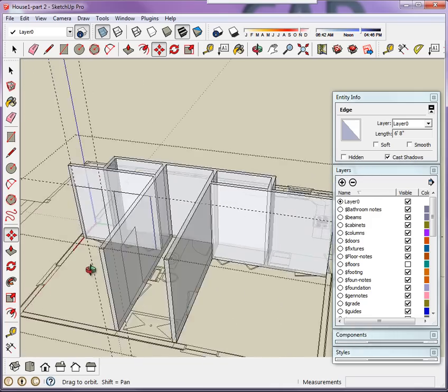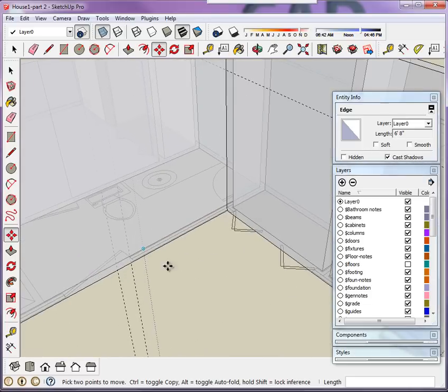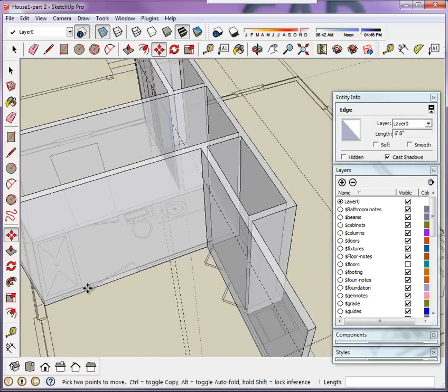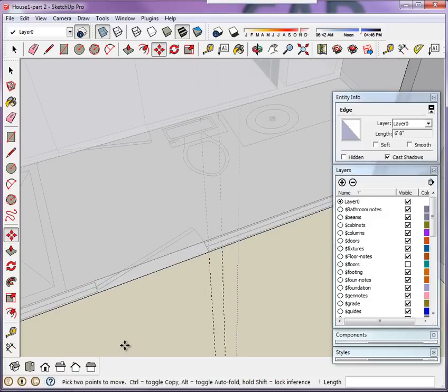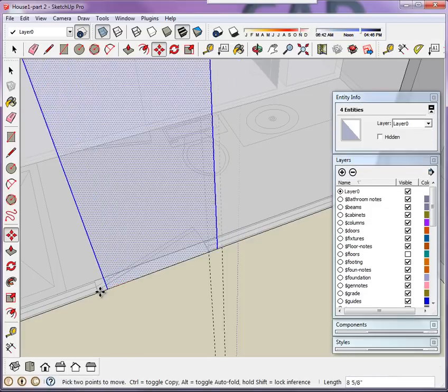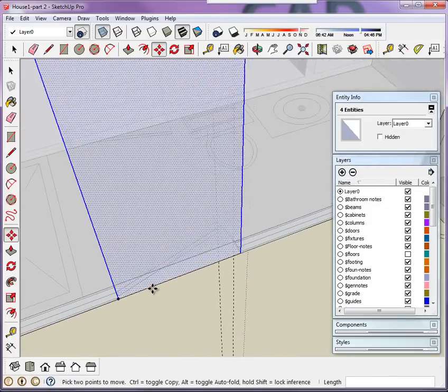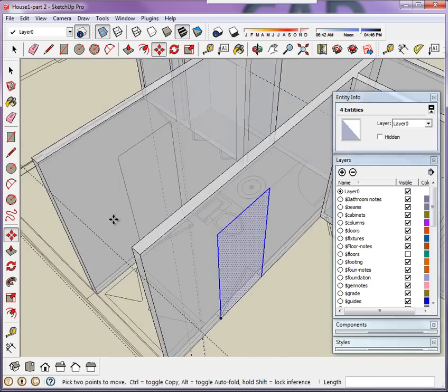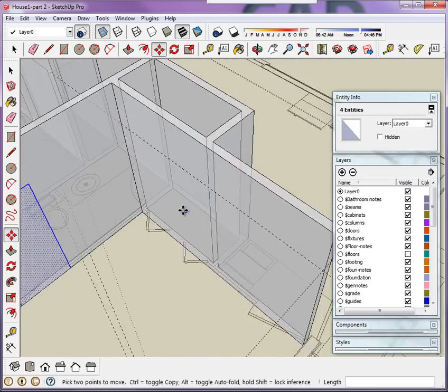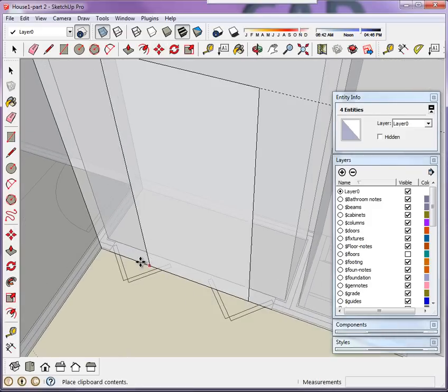Right, so I'm about to create all these openings with just one profile. Okay, one more time over here. I'll position myself, Control V for paste. Get it aligned somewhere, and then zoom in to drag close to the opening. All right, let's do the closet. Over here, Control V to paste.